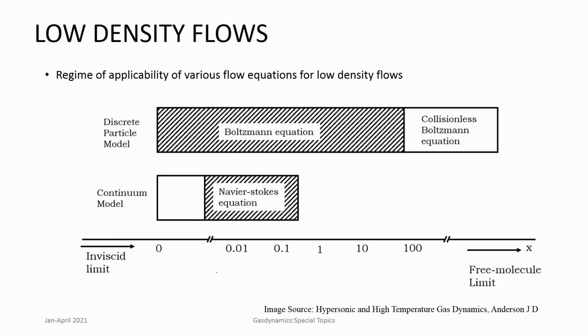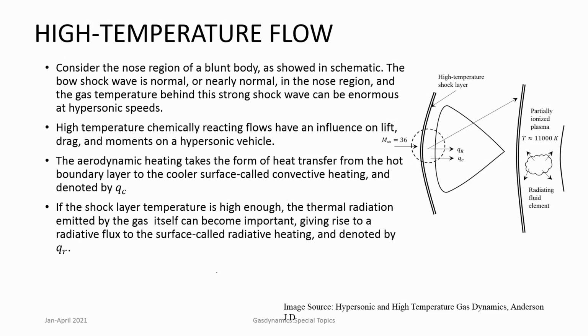Whether continuum actually applies or not has to be evaluated by looking at the Knudsen number carefully. So, when we do analysis of hypersonic flows, it is always good practice to calculate the Knudsen number first, and then find out whether we can continue with the compressible Navier-Stokes equations, or we have to use other equations like Boltzmann's equation and so on. Okay, so those are also a part of looking at hypersonic flows.